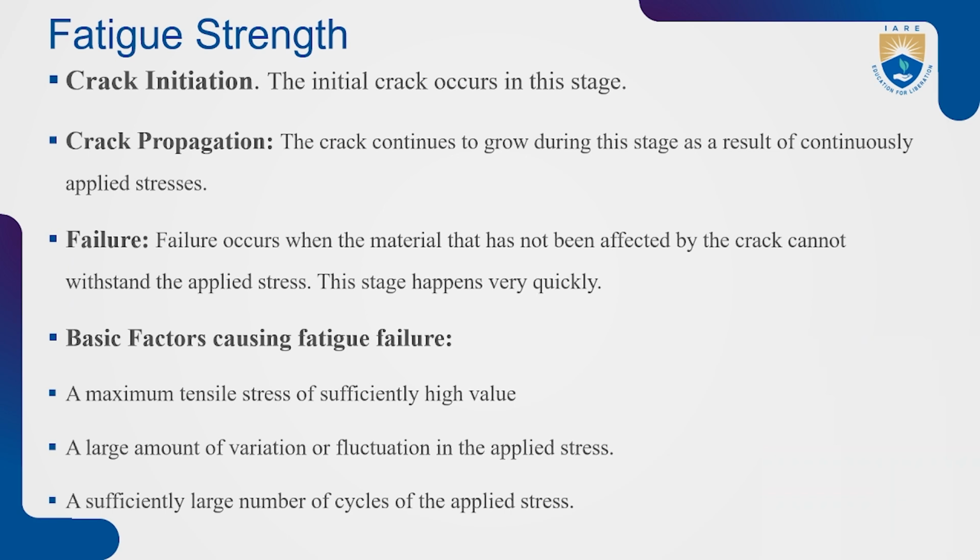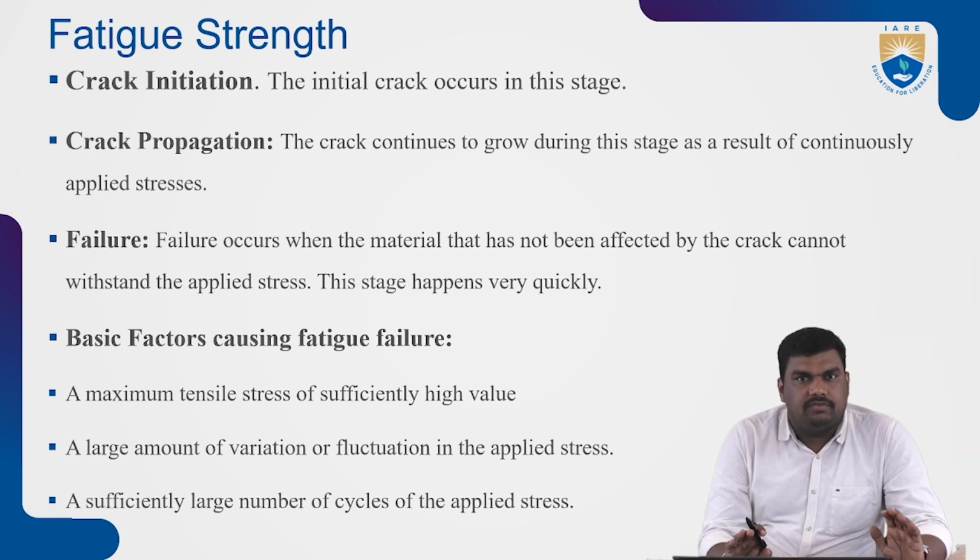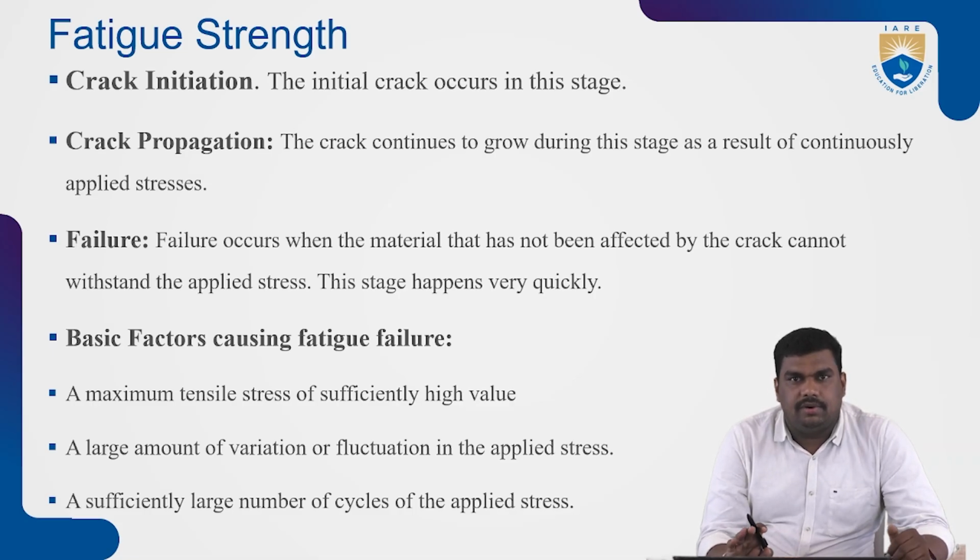Fatigue initially, so just let us recollect that. What is fatigue? Fatigue is generally the number of stress cycles before failure, that is, how many cycles the material can withstand. That is your fatigue strength. The cyclic stress will be combined, or multiple loads will be acting on a component.